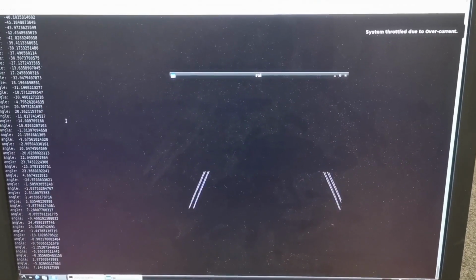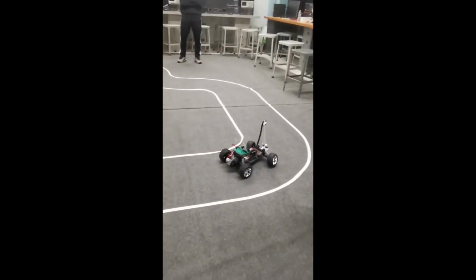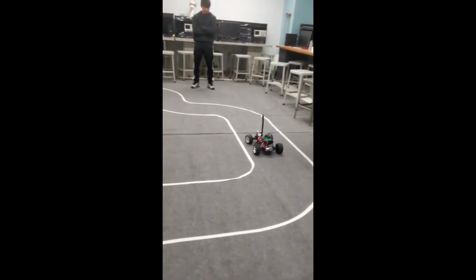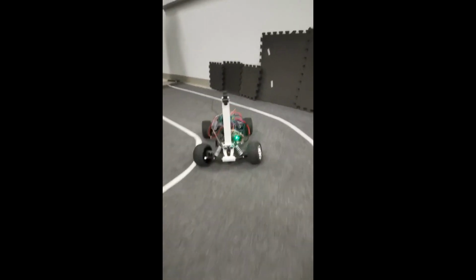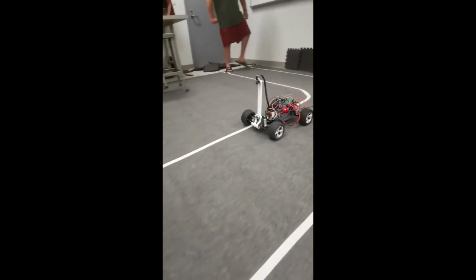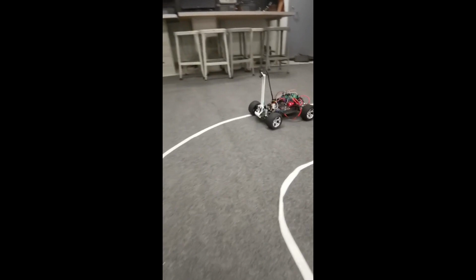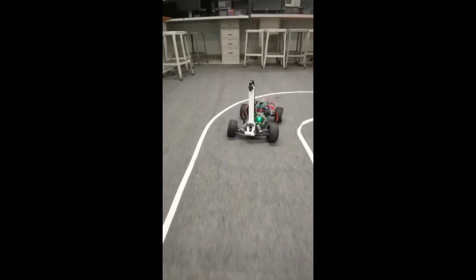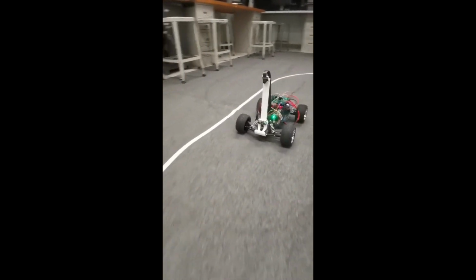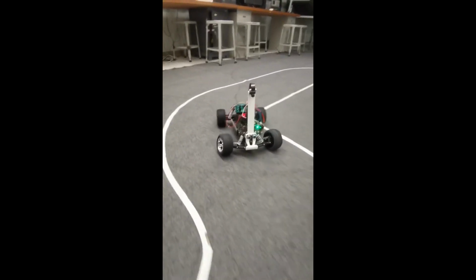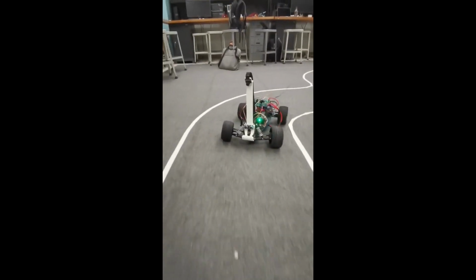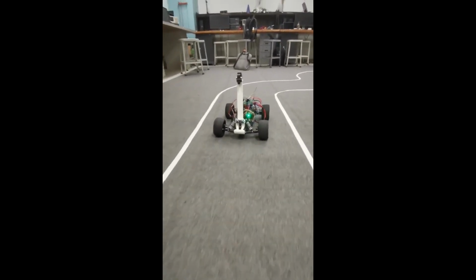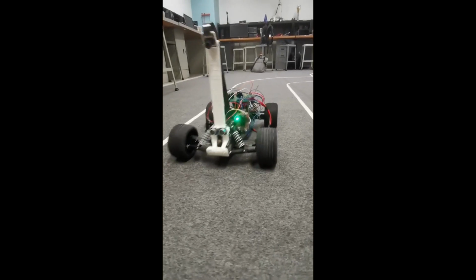To ensure stable car movement, we identified an issue with our servo hardware, which causes the car to have limited left turning ability and slower response time compared to right turns. To address this problem, we have modified the PD controller. Instead of using a single set of parameters KP and KD for both left and right turning, we now have a separate parameter pair for each direction, resulting in a total of 4 parameters that require tuning.